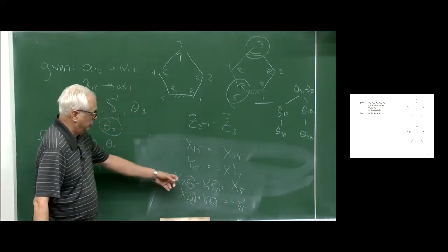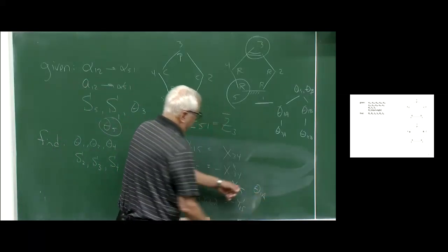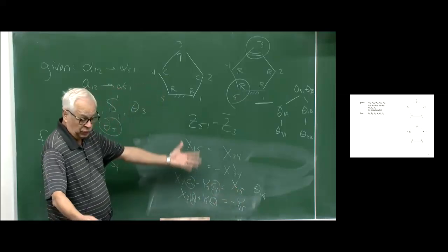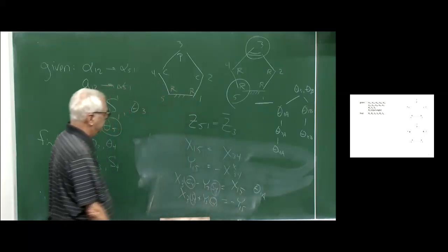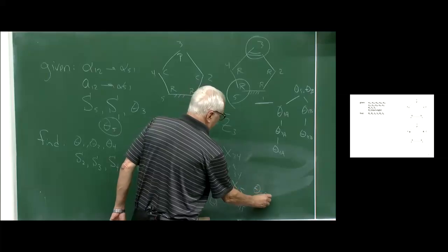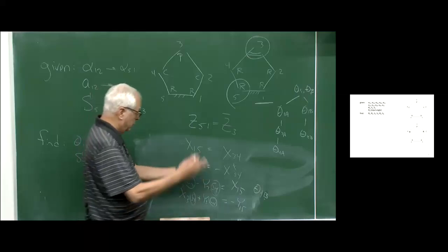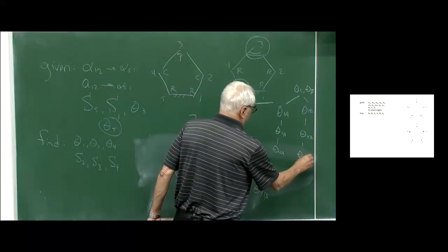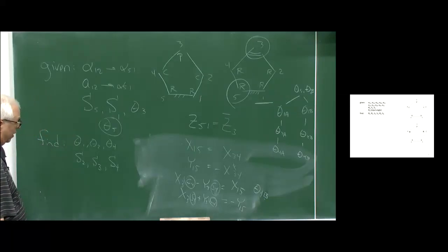We're going to take the given theta 3, turn those into numbers, take the given theta 5 and theta 1a, numbers, solve 2 equations, 2 unknowns for the A case. Then we're going to take those same 2 equations, put in the given theta 3, the given theta 5, and theta 1b, get new numbers on the right-hand side. Solve 2 equations, 2 unknowns, get the sine and cosine of theta 4 for the B case. And boom. So on this group 1 mechanism, this is what's going to happen every time. We're going to be able to solve for the A and the B case of the joint angles based on the material we did in chapter 6.